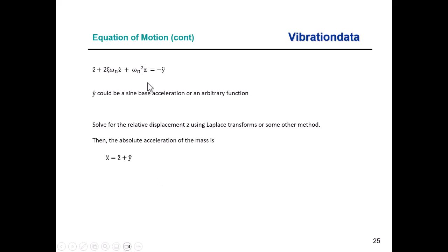So the two things we're looking for in terms of that spring mass response: what is the relative displacement? You can think of that as being the spring displacement if you like. And what is the absolute acceleration of the mass? Those two output parameters are dependent variables. Later on, we're going to be looking at another parameter called pseudo-velocity, but let's save that for later on.